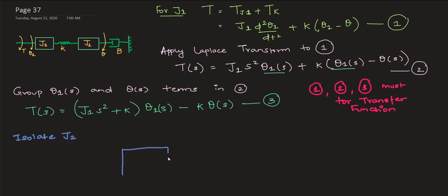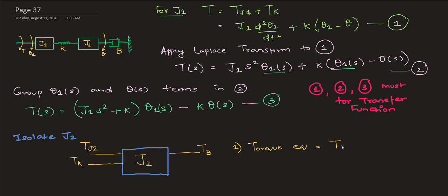That means we are taking both the inertias in consideration when computing the transfer function, and the transfer function obtained represents the system as a whole. So when I make decisions about my system with the help of my transfer function, I am deciding for the entire system and not with respect to either J1 or J2. That is what these substitutions of equations mean.